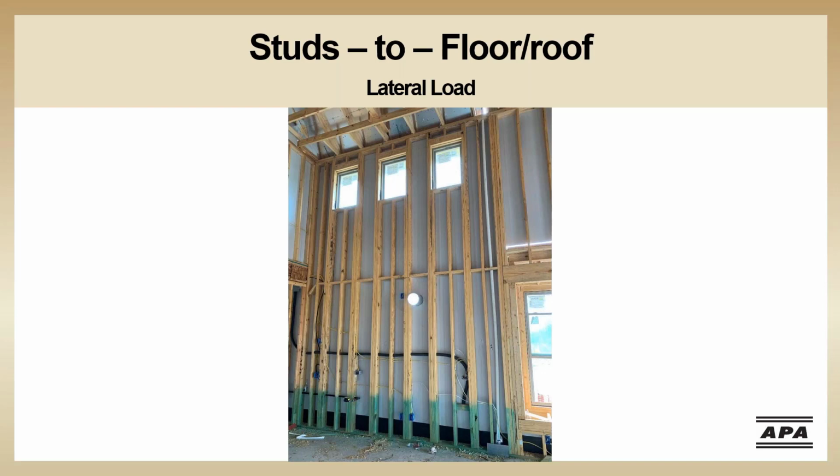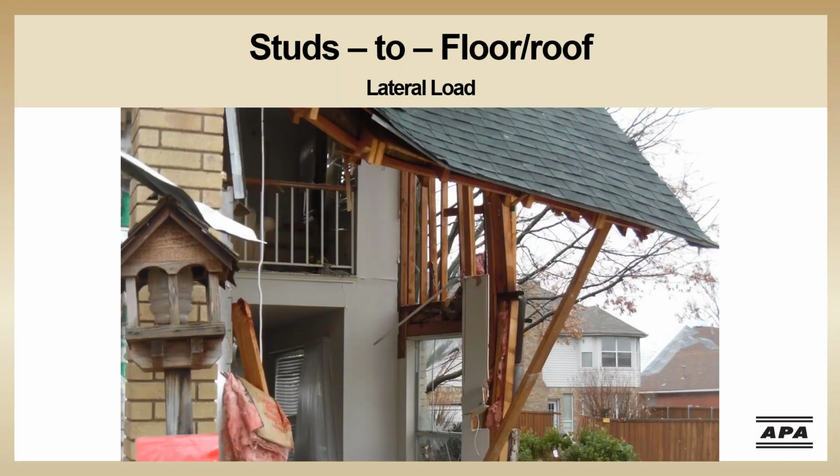Let's take a look at an example of what I'm talking about. In this photo, you can see the hinge failure here. The wall in this room is mostly gone, most likely because of the failure in the lateral load path at the studs. The connection between the stacked walls does not have the necessary rigidity to transfer a wind load. If there had been a second floor in this room, the floor sheathing would have been available to take the wind load and support the studs. Without a second floor, the two-story stacked wall should have been a continuous stud wall from floor to roof.